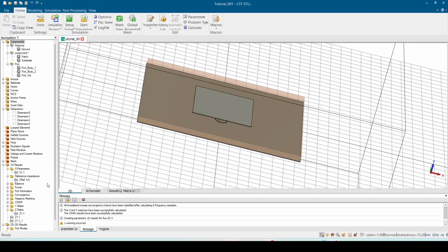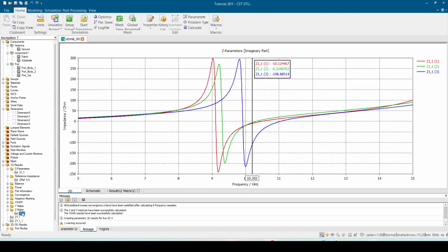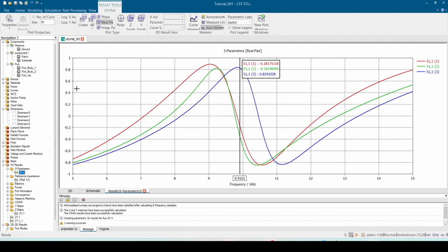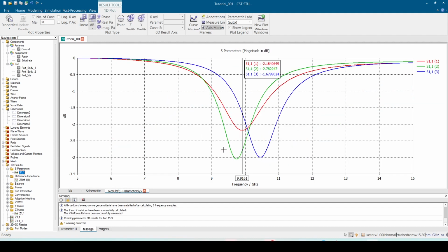Well, the simulation is done, so we can look at the Z parameters. We can see the shifting almost from the same number, because I just multiplied, not accurate. I just wrote 9.3 over 10, but it brings me the resonance very close anyway. So it is linearly proportional. And then the Z parameter and the S parameter, let's just have a look at the matching. You see it's literally we shifted only with the same percentage we want.